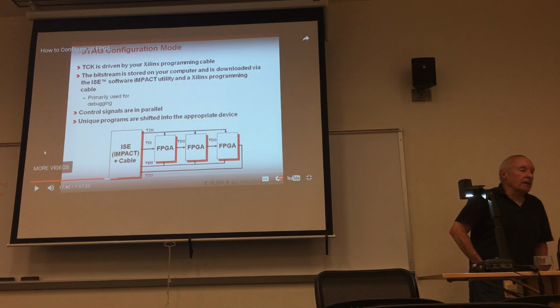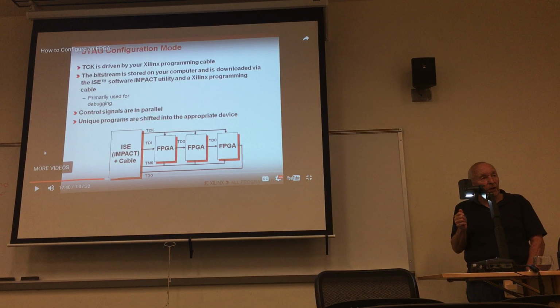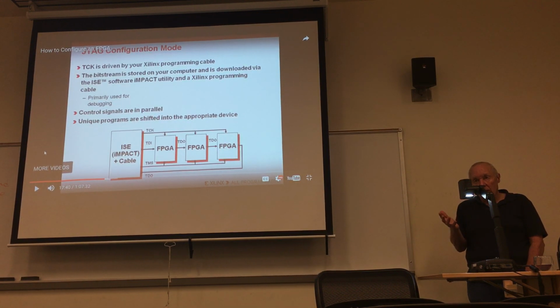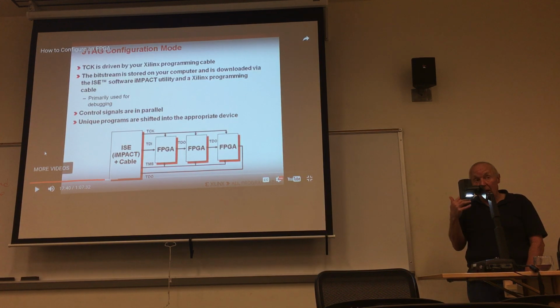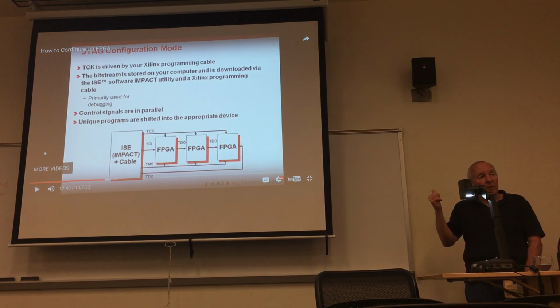The other important thing is he said that this JTAG overrides any other configuration mode. So if I picked a SPI configuration mode and I plug in JTAG, that allows me to override the SPI, and the computer will be providing the configuration information, not your flash memory.